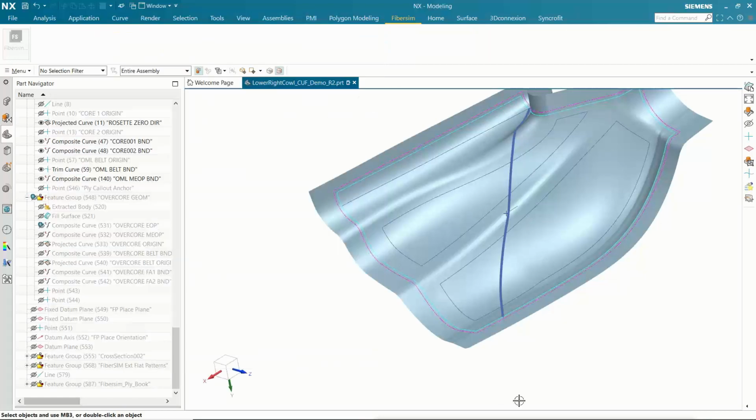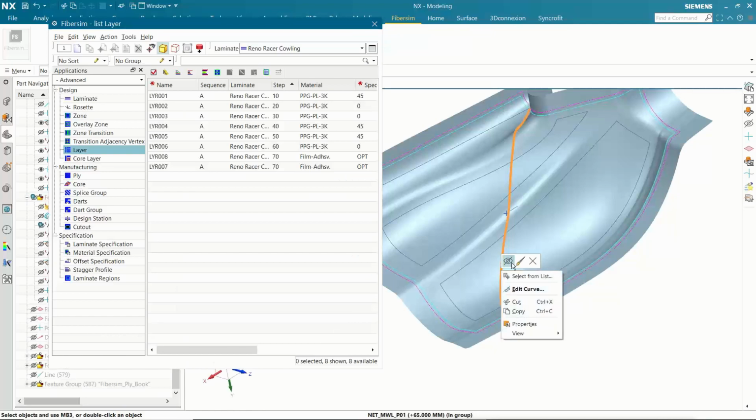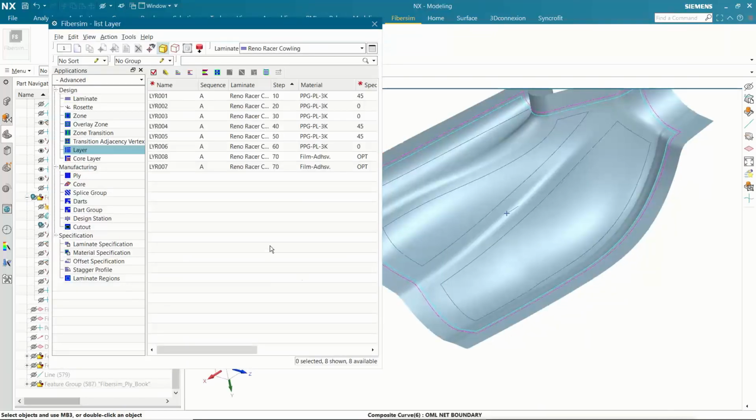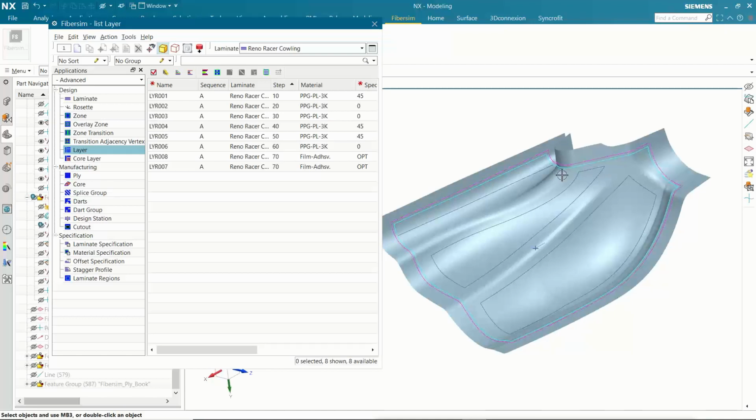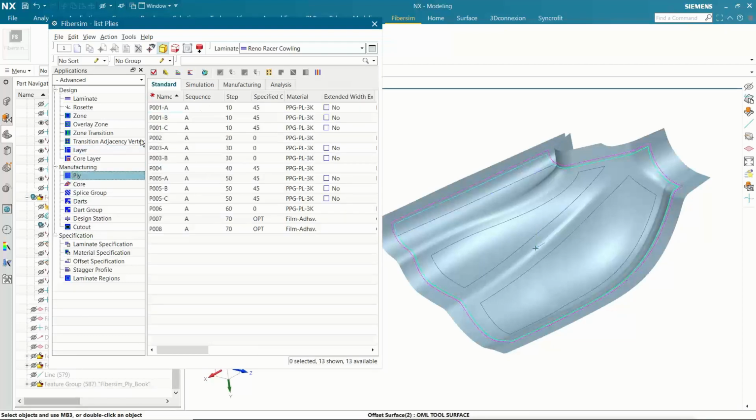The next thing I'd like to do is walk you through what I did for the design itself. So the one ply you saw in the PowerPoint had that severe problem up here with the wrinkling. So I went ahead and I spliced this part up. So these are the different layers that you saw. If I go to the ply list, you can see the different plies that I've created. So I have a 45-degree full body, which was spliced into P1A, B, and C.